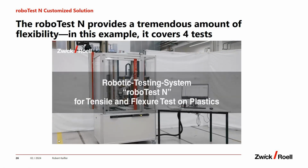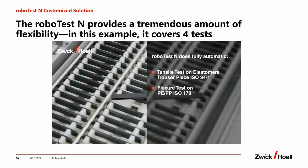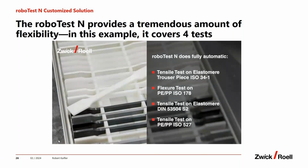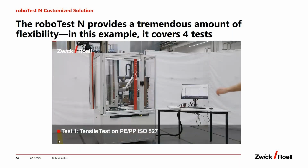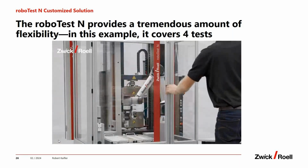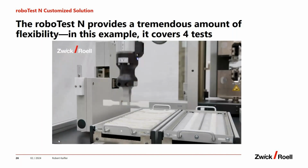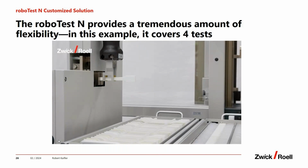First, we are having a look at the samples. We are covering the trouser piece, the flexure test, the tensile test on rubber, elastomer, and the tensile test on rigid PE/PP. Test number 1, PE/PP. You see me feeding the robot. You place the magazine rack inside, then you start the robot. The user is presetting which test is done. Then we make the cross-section measurement at 3 different positions.